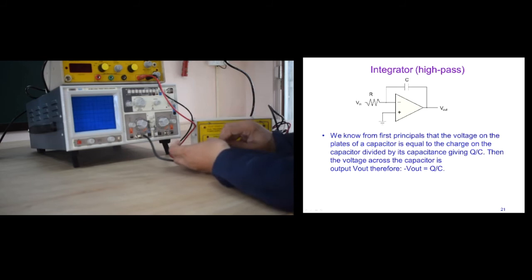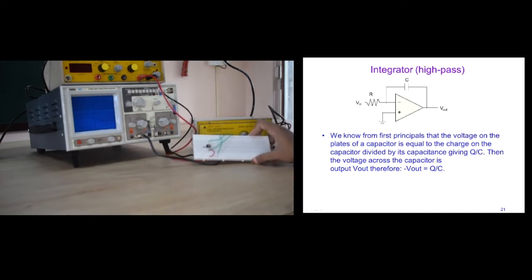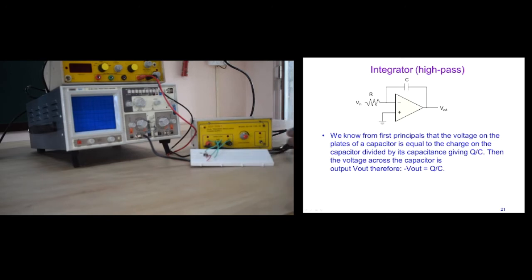And the green one will connect it to the ground line, which we used on the breadboard horizontal line. In such a way we are going to connect the circuit. Now we will just need to connect the input through the signal generator.